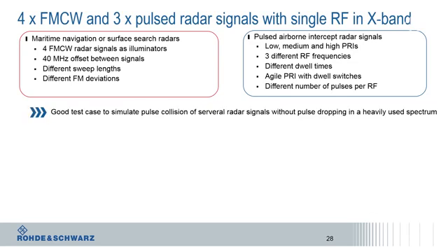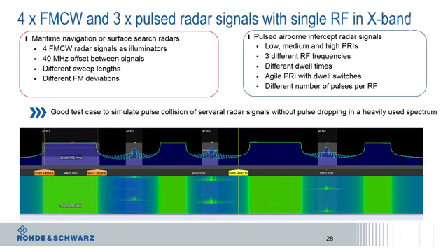This is a good test case to simulate pulse collision of several radar signals without pulse dropping in a very heavily populated spectrum. I use a wideband receiver and some analysis software to look into the generated signals in detail. In the lab, you could inject them into your DUT. And here is the measured result.